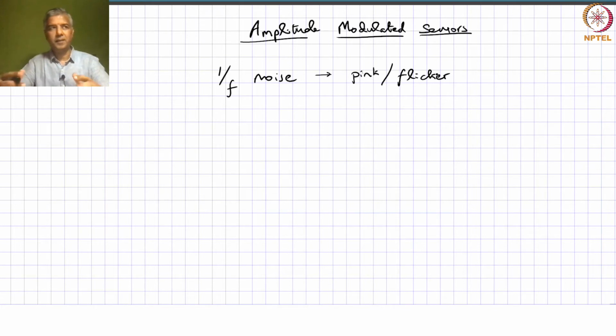We're familiar with Johnson noise, which is another name for thermal noise, named after this person Johnson. When Johnson was making these measurements, he noticed this 1/f type noise at low frequencies that he was not able to comprehend. But he was the first one to report such noise, and that was subsequently termed flicker noise.